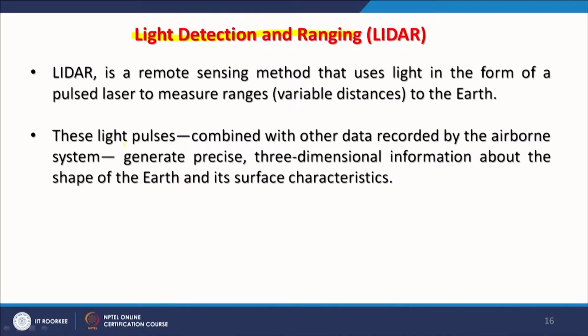When the survey is being done by LiDAR, you do not basically see the light because it is in the form of a pulse, just a very short illumination, and these light pulses combined with other data recorded by the airborne system generate precise 3-dimensional information about the shape of the earth or its surface characteristics, that is basically a digital elevation model. Earlier it started with ground based radars, it used to be installed on a vehicle and so on. Now the instrument is going airborne or spaceborne.